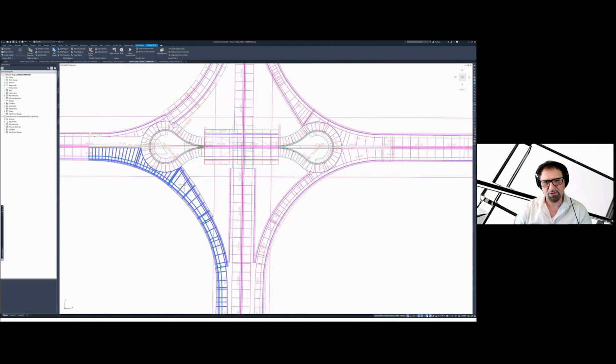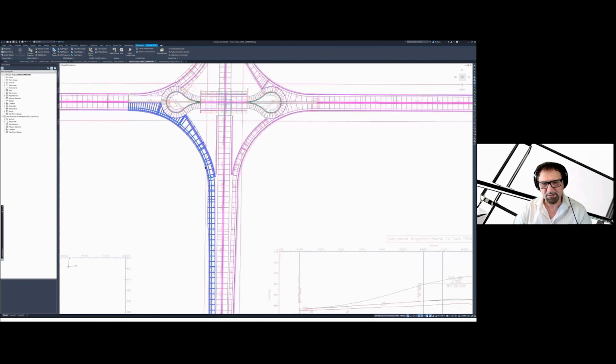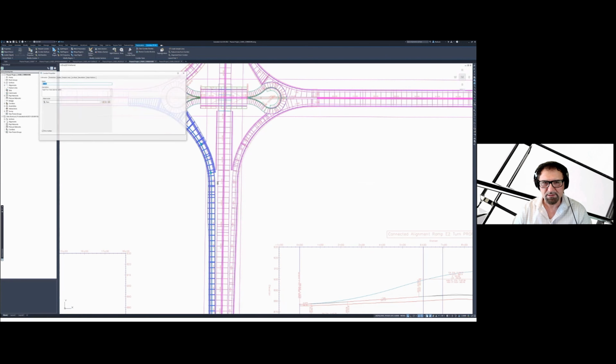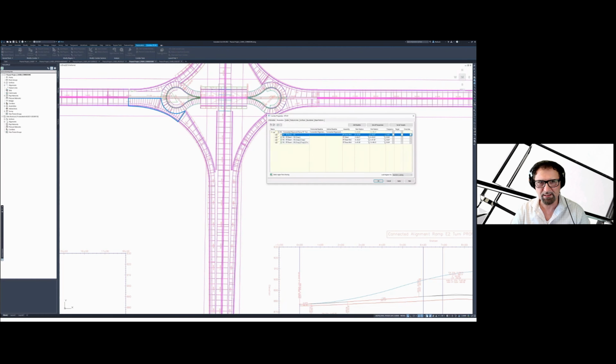So this corridor object for that on-ramp is divided into 3 parts. And if I go to corridor properties, it's not that hard to match them because I'm using that temporary surface. And I'm deriving the profile. So wherever it is on the surface, I'm staying on that surface as much as I can. And so I have no left shoulder in the first region. That's highlighted right there. And then I have